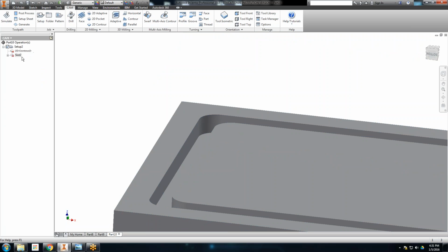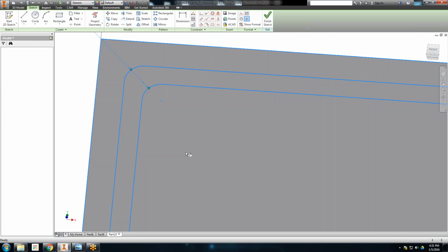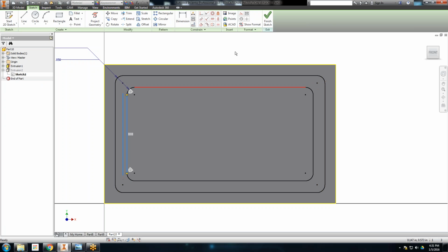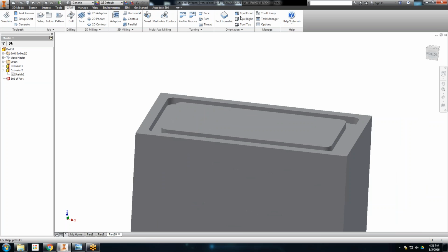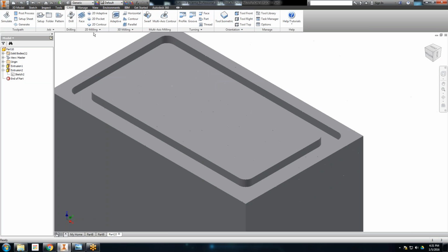Let's see if this slot, nope, see, for some reason, every once in a while my kids can get it to work, and this time, like, oh, I may have too big of a tool. I don't even know how. I just drew this up real quick. So I don't even know what kind of distance I have here. So I was trying to do it with a 1/16 inch tool, and I don't even have a 1/16 of an inch in there. So I've got to go back in and, so I didn't do that with any dimensions, so that's why it's not liking that slot.